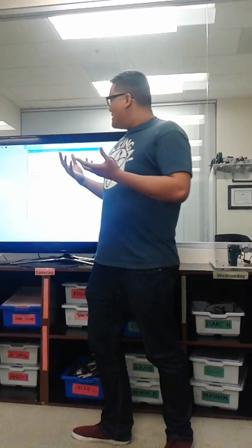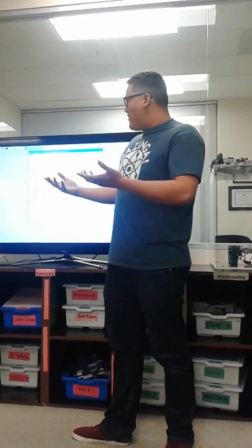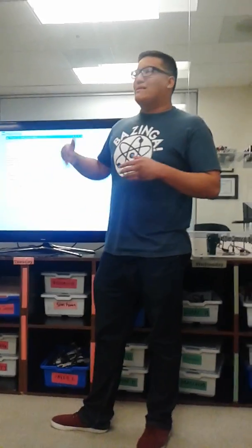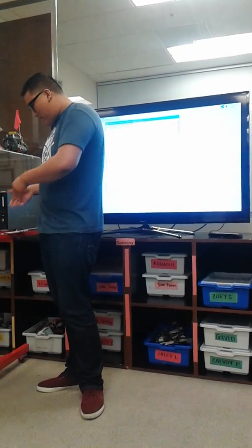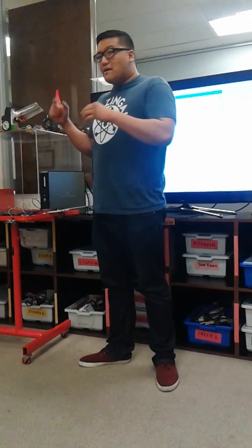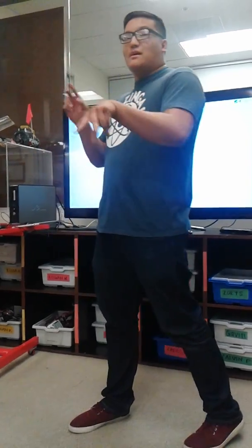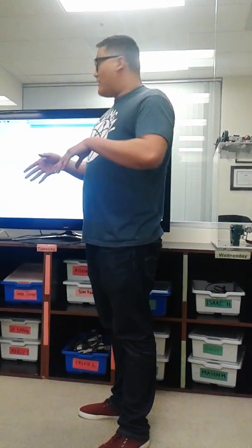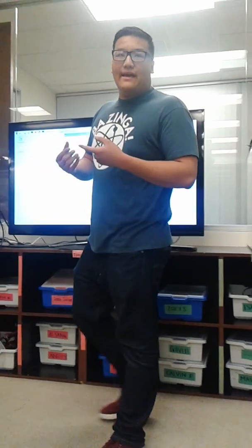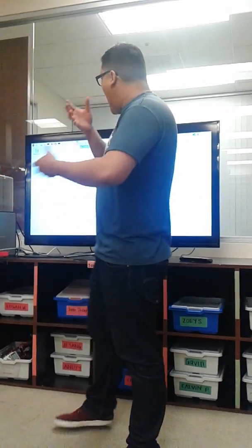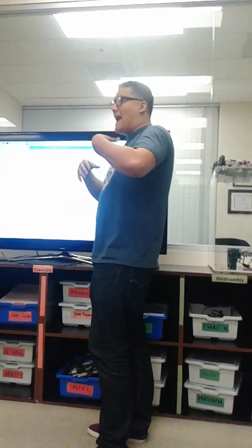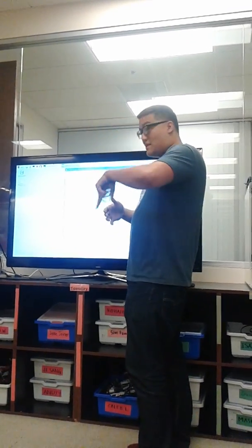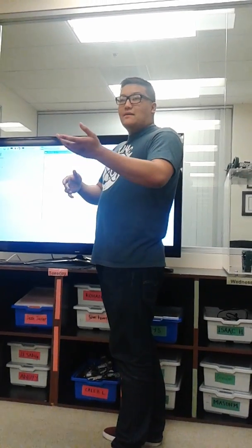Next, I named a variable trig as 7 and echo as 11. The reason I chose 7 and 11 is because in the Raspberry Pi which I use, I use the number 7 prong and the number 11 prong. And these two prongs are just general inputs and outputs. And afterwards, I named the number 7 prong as my output and my number 11 prong as my input.